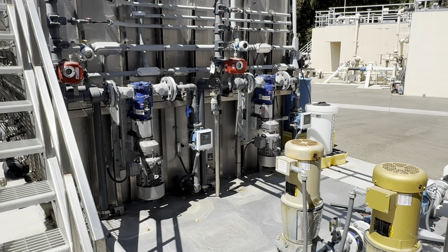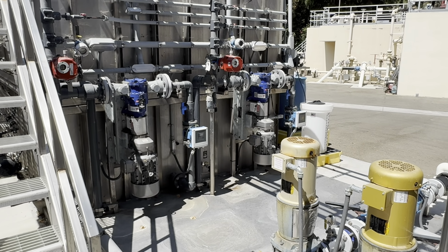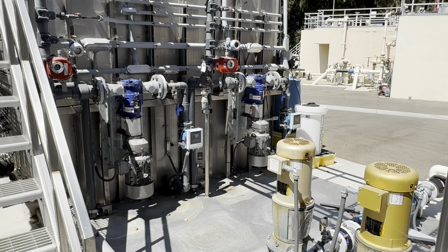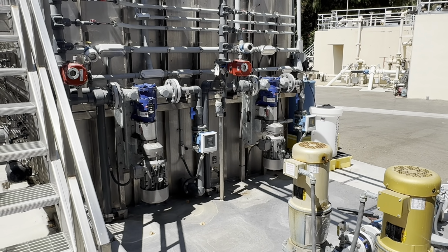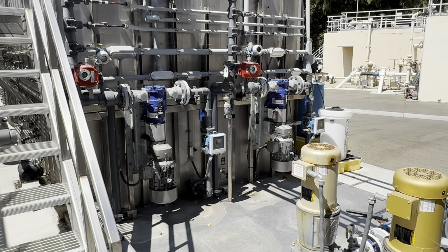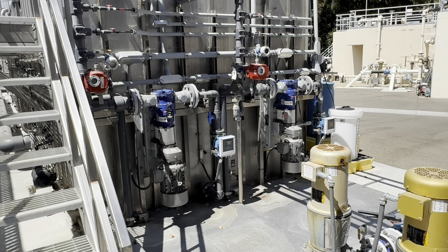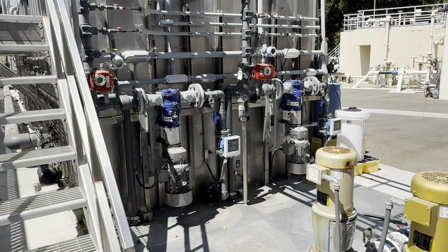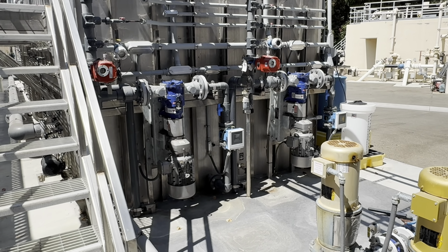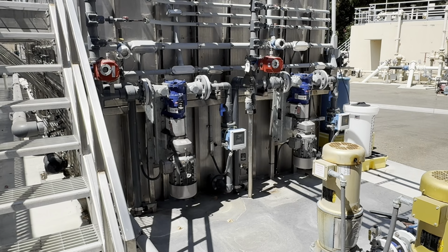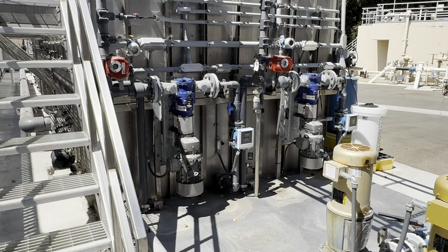You typically have an acid and a base of some kind. Our base is sodium hypochlorite. We use it to burn off the biology off the filters. And then the citric is to descale. And soon I have to do a recovery clean. It's going to be really great. I'll actually have one of the chambers empty at a time and do an acid bath to it and a base bath. We're going to fill up the chamber with a certain amount of chemical per the manufacturer's instructions, and I'll take you along with me for that.